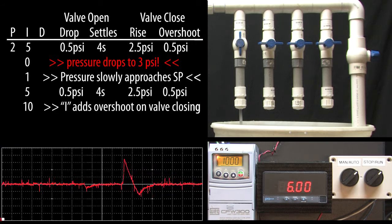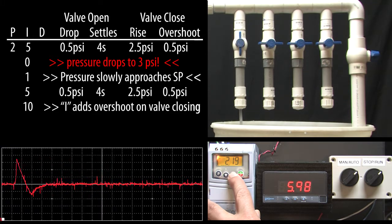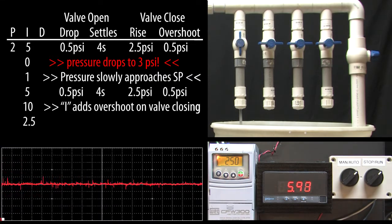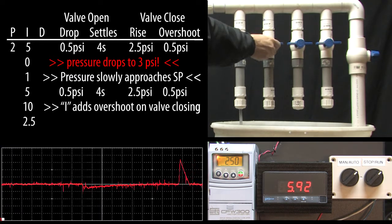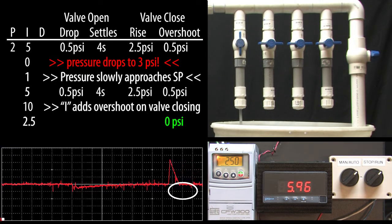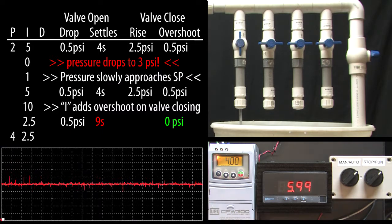So that begs the question, could we reduce I and increase P to get a faster response with a smaller overshoot? Sure. Let's cut I in half and run a quick test. Yep, no overshoot, but it is taking about 8 or 9 seconds to settle. Now let's double P, which is also doubling I back to its original value.